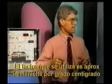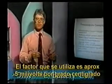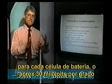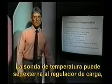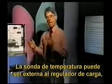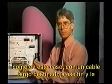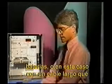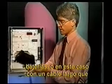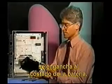The factor that's typically used is about minus 5 millivolts per degree C per battery cell, or about 30 millivolts per degree C for a 12-volt battery. The temperature probe can either be external to the charge regulator, as in this case, with a long dedicated wire and the probe itself taped onto the side of your battery, or in this case, another example of an external probe where we have a long cable and the probe that can actually clip on or tape on physically to the side of your battery.